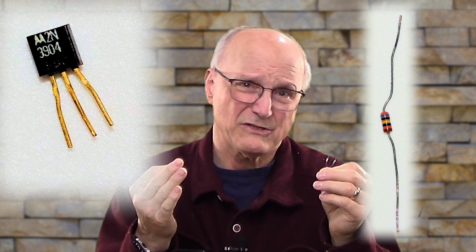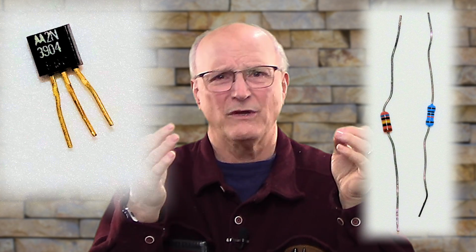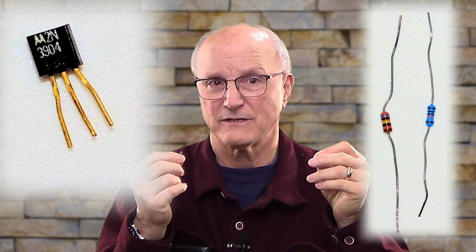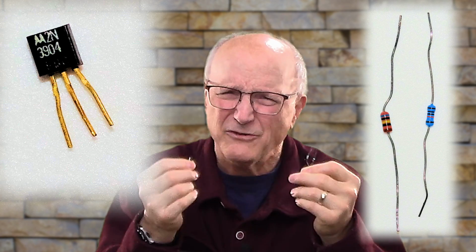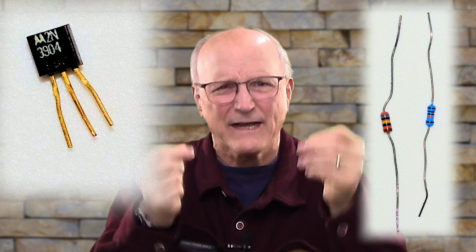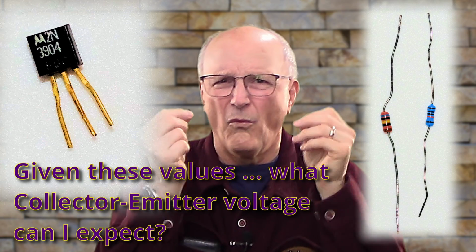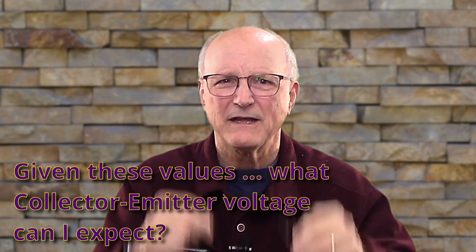Unfortunately, the closest resistor I could find to our calculated 226 kΩ resistor for the base resistor was a 221 kΩ resistor, which actually measures 223.8 kΩ. Well, these are not exactly the values I calculated, so I have to ask the question, given these values, what collector-emitter voltage can I expect?